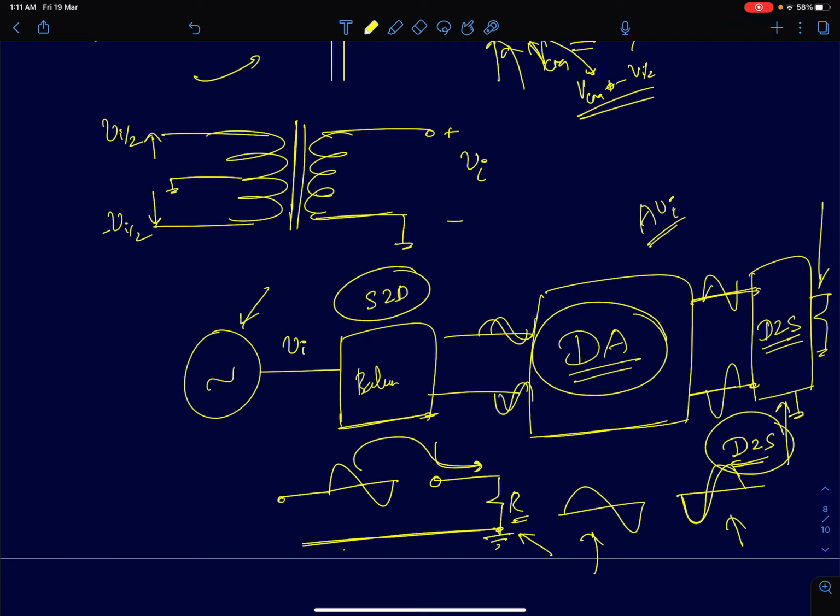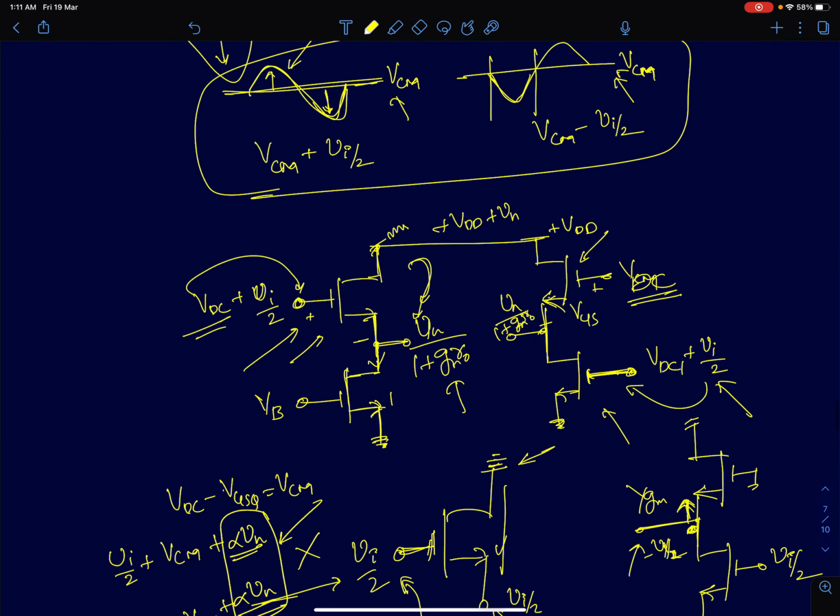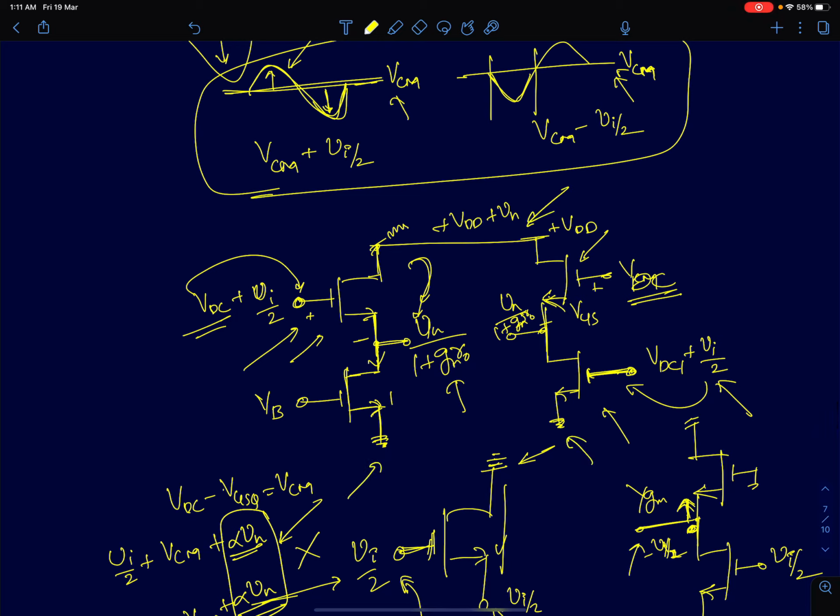So this comes with an advantage. So far we have discussed differential amplifiers. One of the main reasons is that differential amplifiers will not react to common mode changes. I'm calling the ground and supply noise common mode changes, and differential amplifiers are not going to respond to that. That's one huge advantage of a differential pair. As we discuss differential amplifiers in the upcoming weeks, we will see a lot more advantages, how they evolved over time, and their penetration into integrated circuit operational amplifiers. That will be the topic of the next few lectures.